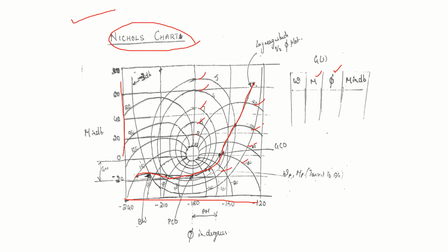And that completes our discussion on Bode plots. Here, how to take the open loop transfer function, how to construct the Bode plot for each one of the factors, both magnitude plot and phase angle plot, then how to draw the resultant magnitude plot and resultant phase angle plot, then what is gain margin, phase margin, how to determine gain margin and phase margin, then how to get the system stability. These things are told.